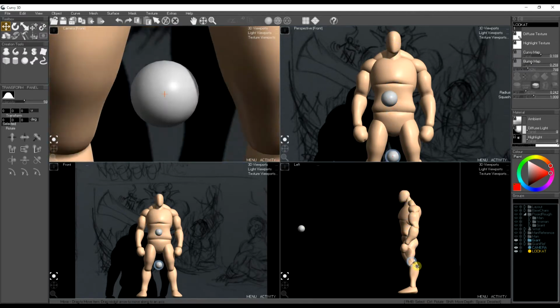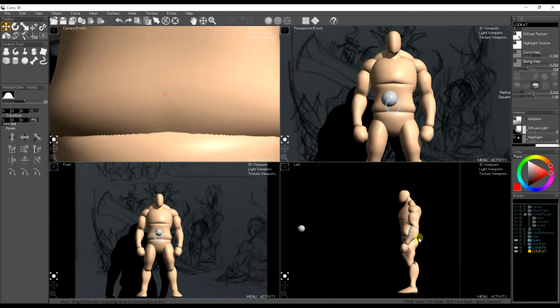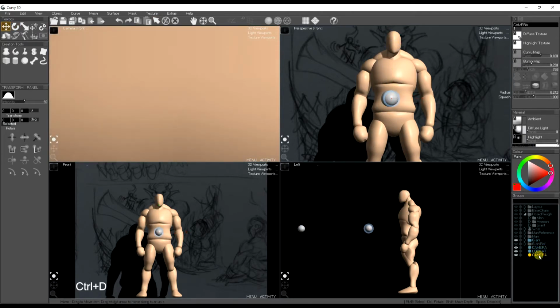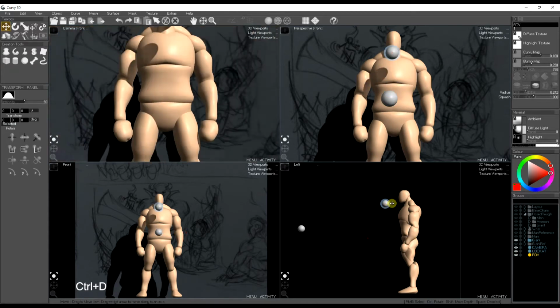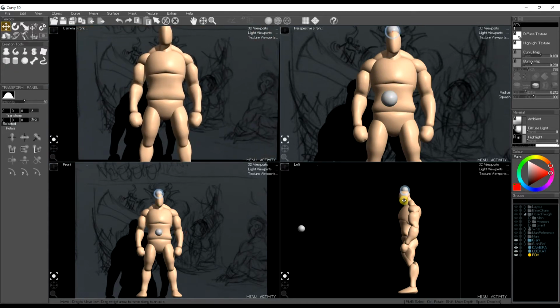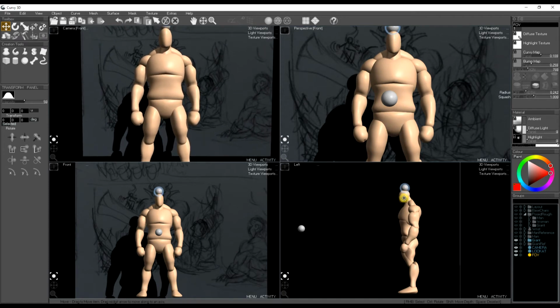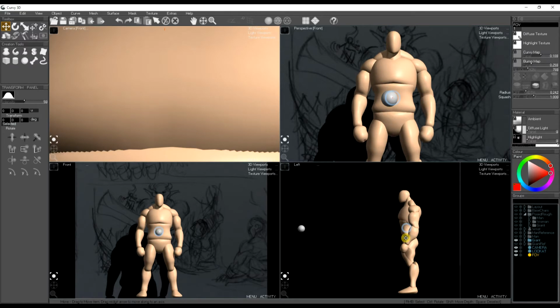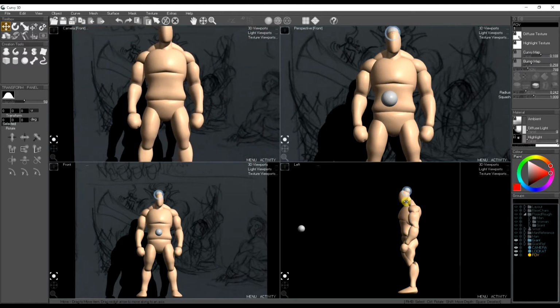the camera is looking. So if we drag it up to the head or down to the toes, that's where our camera viewport will be looking at. And the third one we need is the field of view, FOV, and that needs to sit right at the top in the middle of your image. So if I move the FOV to the top of his head, then the camera viewport will be lined up at the top with the top of his head.